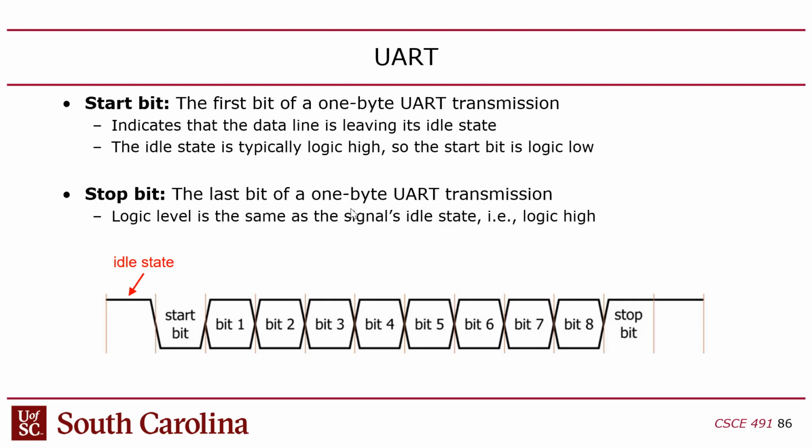But motivation to actually read the data sheet. Right, so that's the problem. In the FPGA, it's really obnoxious because if you use the JTAG over USB connection, which is what most people do, that's one speed. But if you physically connect a serial line to the FPGA, it uses another speed, right? So it's always wildly confusing.